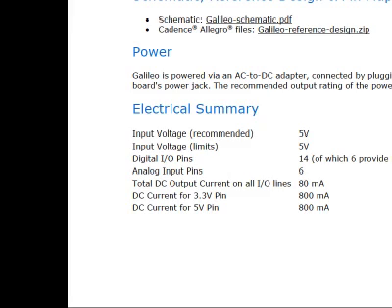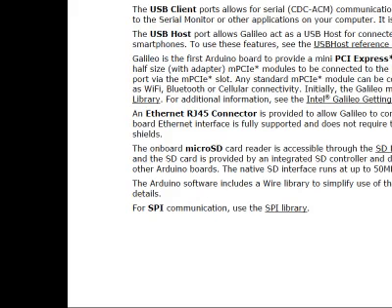As we said earlier, this is an open hardware platform, so the schematic and also the layout files are all publicly available. You can download these files from Intel's website. For communication to this board, you can use UART or USB or PCI Express.